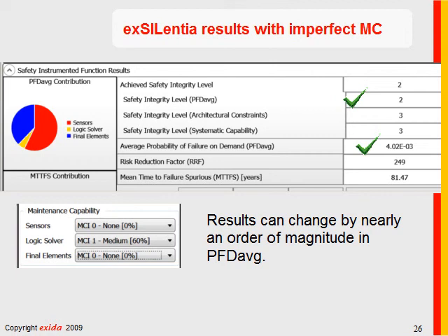So you see what's happening here. Maintenance capability is important. If the OREDA data includes that, then FMEDA results are perfectly aligned with OREDA data. I did ask some of the experts from SINTEF if they had separated the maintenance failure from the product-specific failures. They had not done that, but I was verbally told that, quote, a majority of the failure reports were due to maintenance-induced failures. I don't have any data to support that other than a verbal statement.